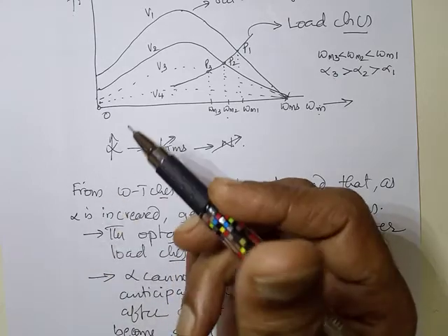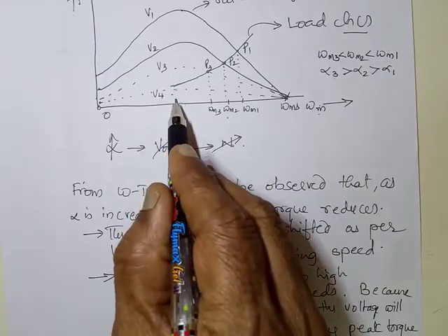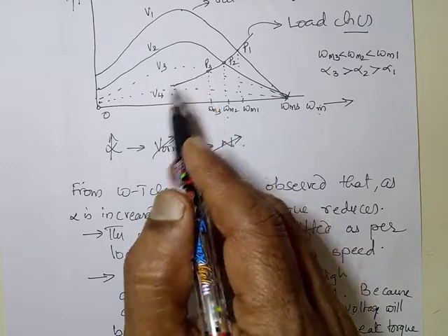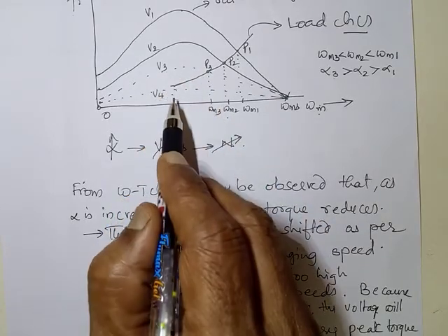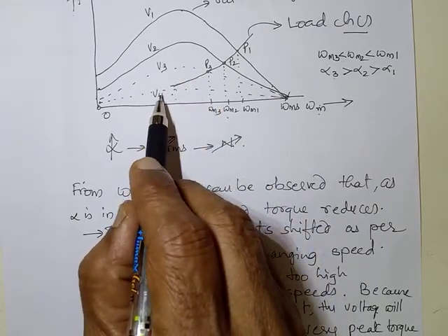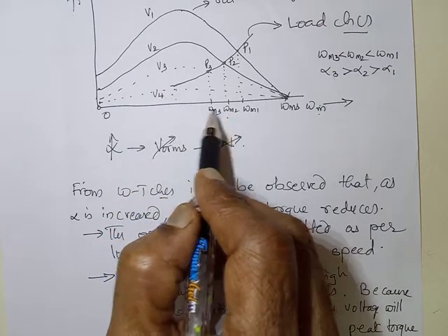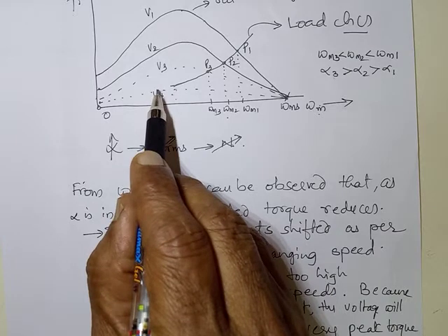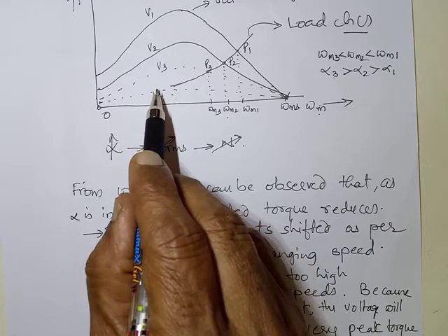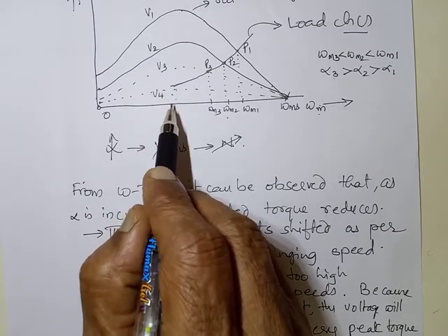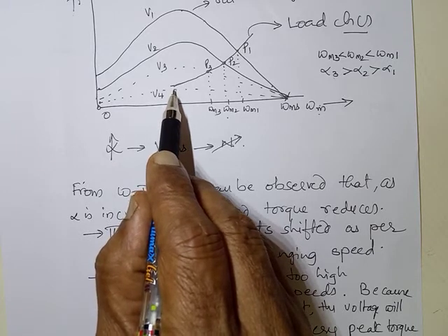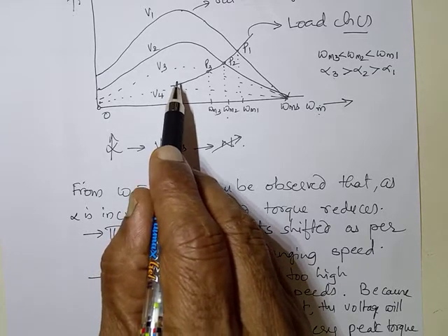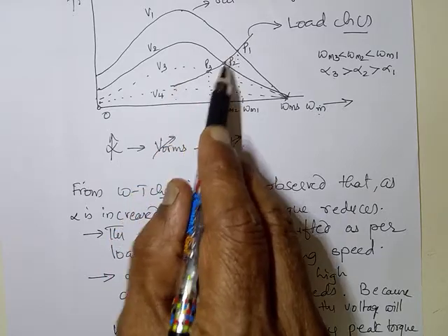The maximum torque is less than the minimum load expected torque. Motor will not run. That means I cannot make the speed too less, because I cannot make the voltage too less. Making the voltage too less might result in the maximum torque itself being less than the minimum torque expected by the load.